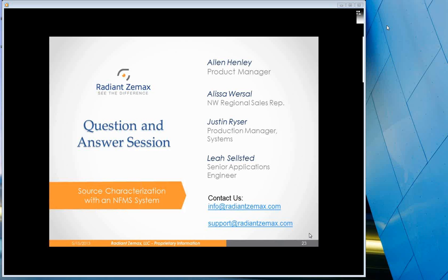There's also a question about whether the IES file or the RaySet radiant source model can contain the spectral data. They can, especially if you're using the optional spectrometer to take those measurements. Right, the RSM itself can include spectral data for each angle. I don't believe IES files include color information. Right.